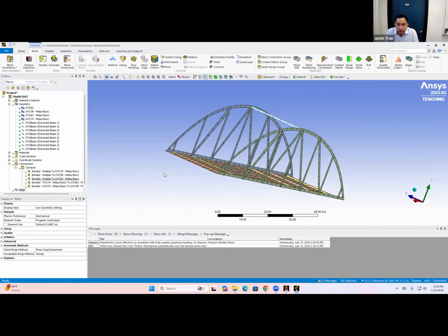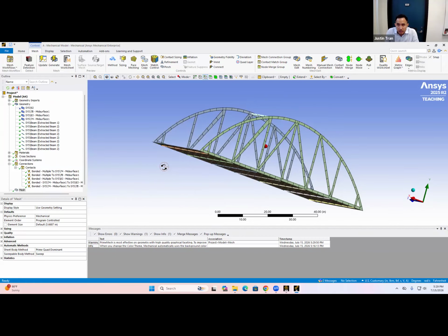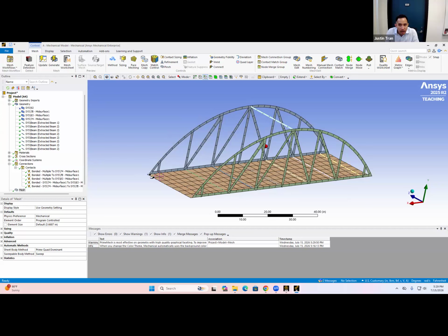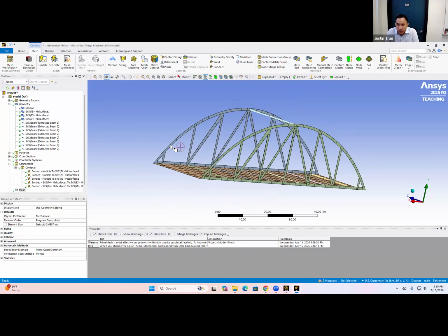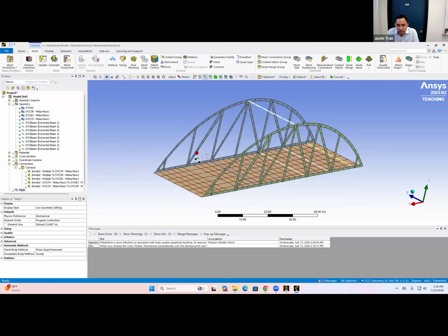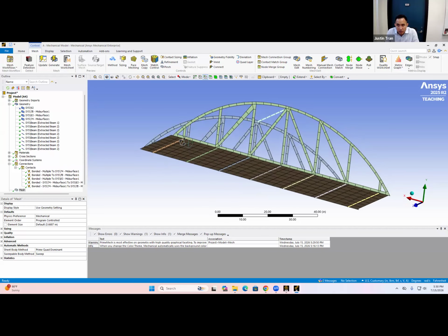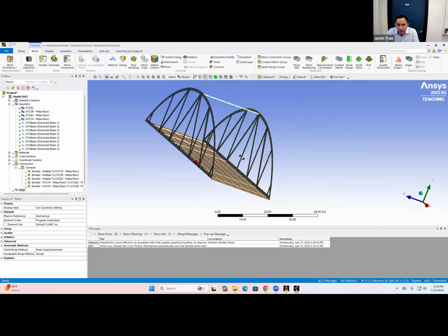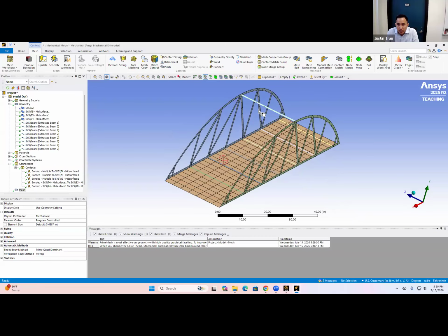Normally we want to apply meshing settings on this to modify the size, but this is going to be fine for our purposes just for now. Notice how the mesh here has shells and beams. So we have 2-dimensional mesh elements for our shell parts and 1-dimensional mesh elements for the beam parts. That's exactly what we want.